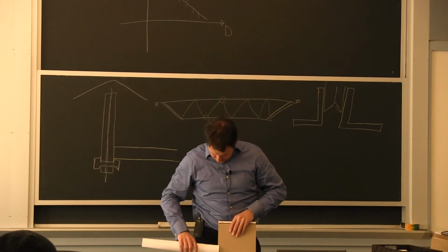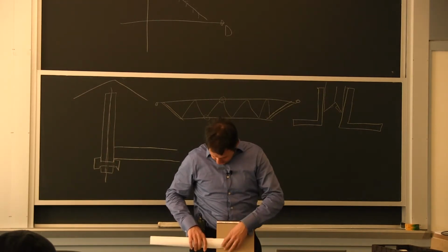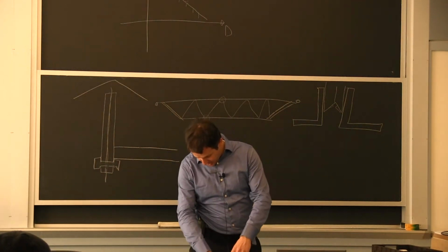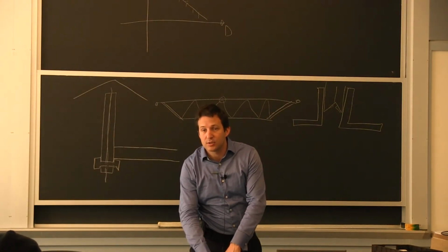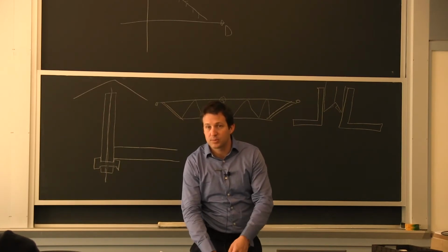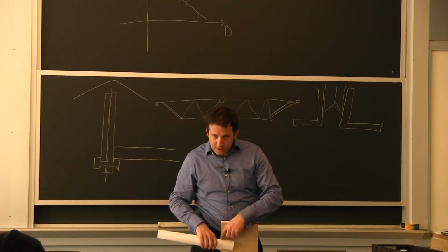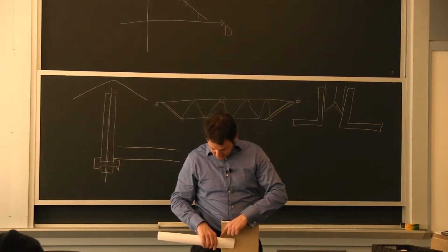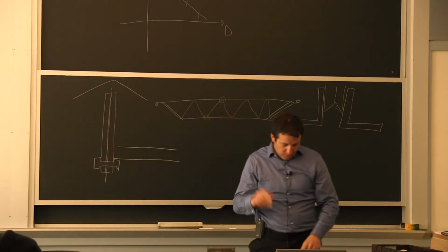They continue. What Professor Eager mentioned was really relevant, and it will come up in one of our examples: not to weld the end here. If I have the notch and I start to weld this little end, now that area is loaded in tension. It's really stiff, but if I start applying cyclic load, I'll start a crack right there. For a crack to go around this way will take a lot of energy because it's in shear, but it just starts to go and break the tube. And we're going to go through an example of that.